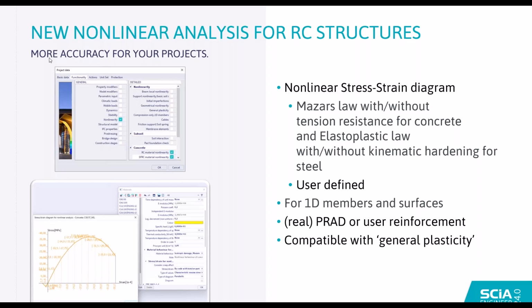You will be able to create those materials for both 1D and 2D elements, and you can perform this nonlinear analysis for both elements with or without reinforcement. The most important part there is that the reinforcement that you add needs to be user reinforcement. So just the templates will not be taken into account.